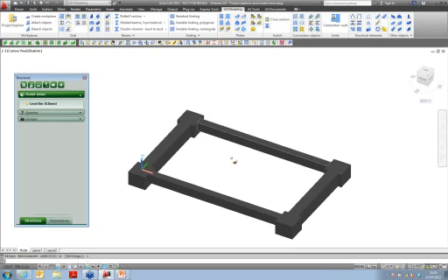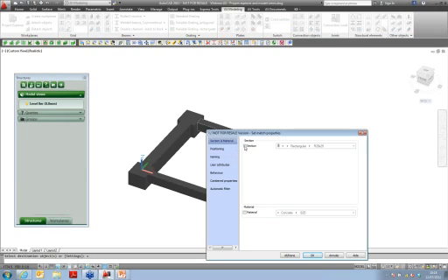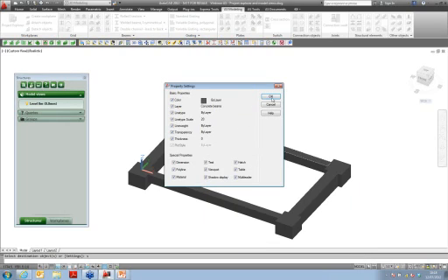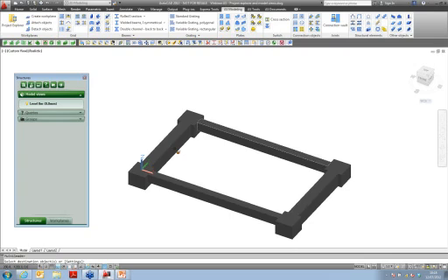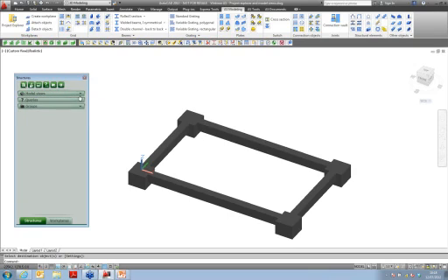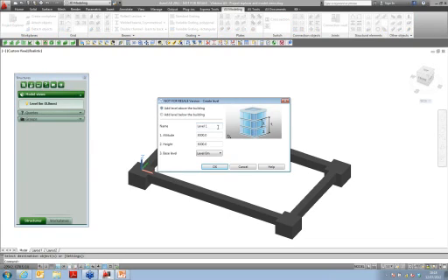Okay. With the settings, I can define exactly what I want to match. Let's say just the section, okay, and also the layer and the color that I want to match on this element and this element. Enter. Here we go. So now I would like to display some other levels. So I go back here in my Project Explorer, make a right click, create level, and I would like to create a level at a specific altitude, let's say